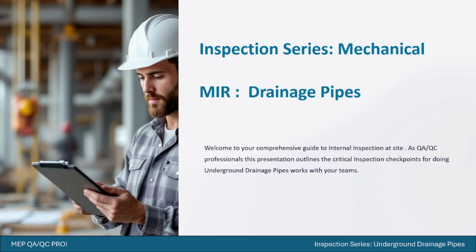Whenever you are receiving material at site, what is your role? You do the inspection internally with your site team and your store team prior to offering it to the consultant or client. As a QA/QC engineer or inspector, you have to do an internal inspection to make sure that whatever material is received at site is as per your approved submittal, approved brand or approved specification. Everything should be checked.